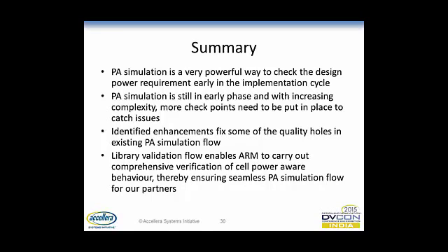Many of the dynamic protocol requirements, and the retention one which we have captured is one of them. There may be other cell requirements, dynamic protocol requirements, which simulators are not modeling right now, and unless they are explicitly modeled in the Verilog, you might not know until it goes to silicon. Static checks don't catch those issues, and dynamic simulators don't have those capabilities.